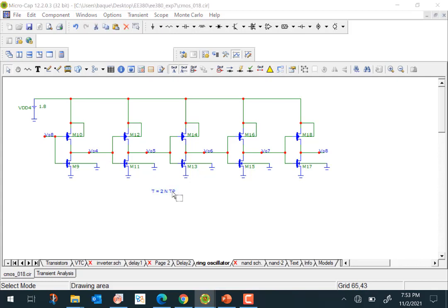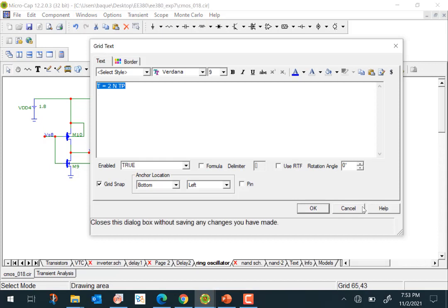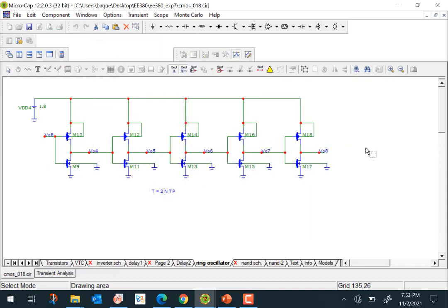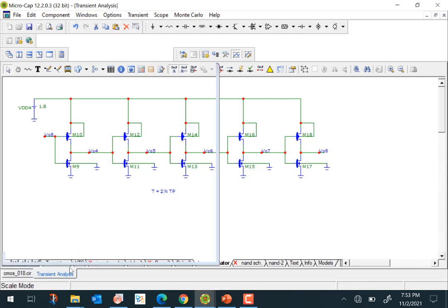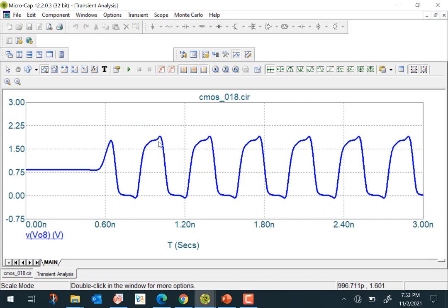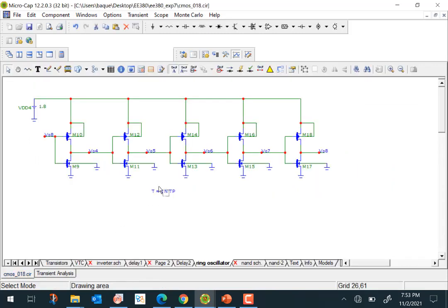So an easy way to measure a propagation delay is to simply make a long chain of inverters. This is 5, but even 5 gives us a fairly high frequency, and high frequency sometimes becomes difficult to measure. So people sometimes make a 32.